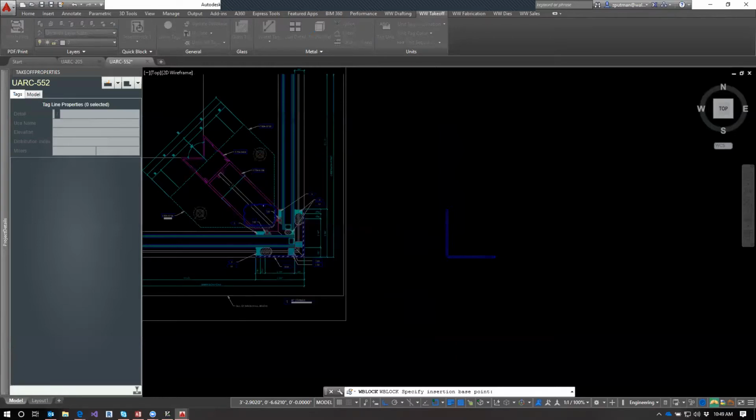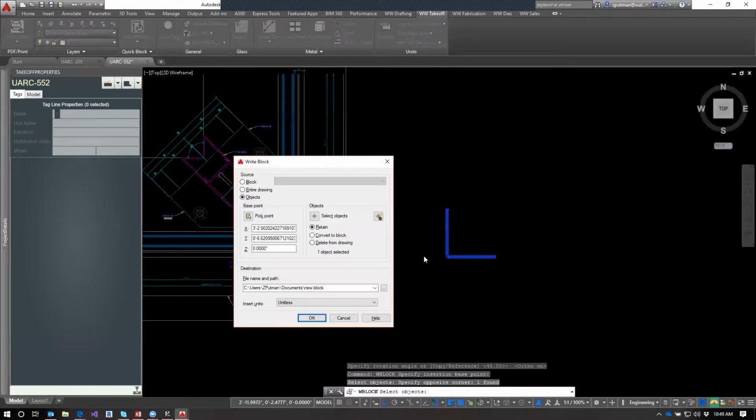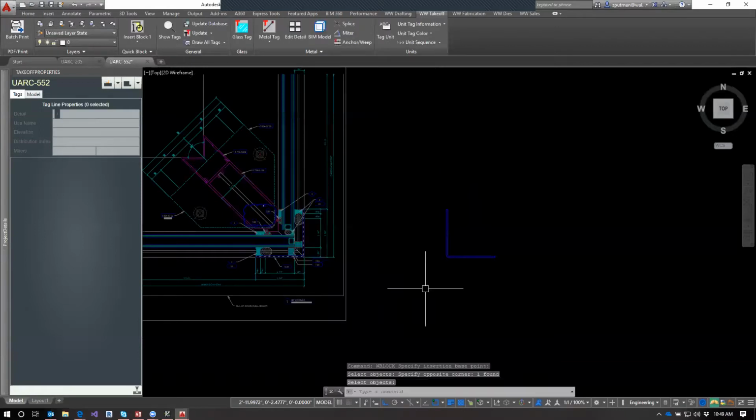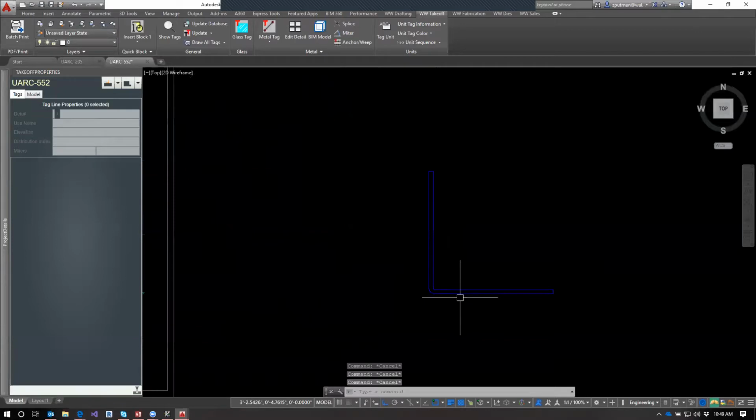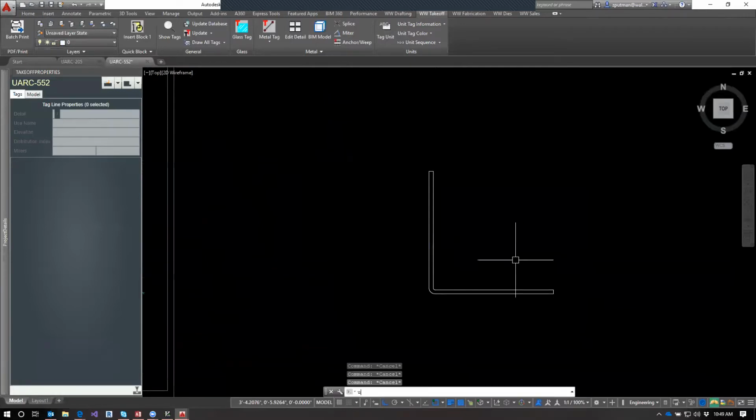The objects I want are these guys. The layer doesn't matter on this. Oh, I should make sure that I can extrude this, because if you make a part drawing and you can't extrude it, it is kind of useless. So one way to check is just to run the region command and select this thing. And if one region is created and the thing is now on layer 0 because your current layer is 0, it should be able to be extruded. So I'll just undo that back. But yeah, I usually use the region command just to check it really fast.